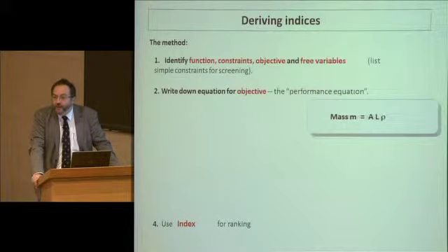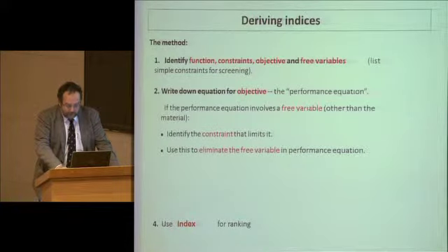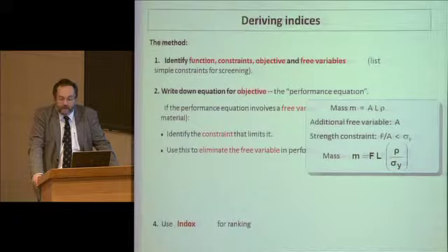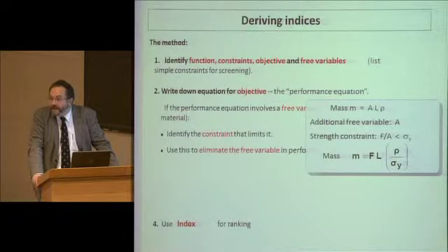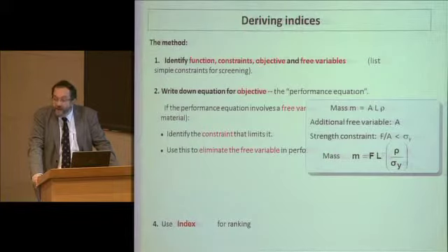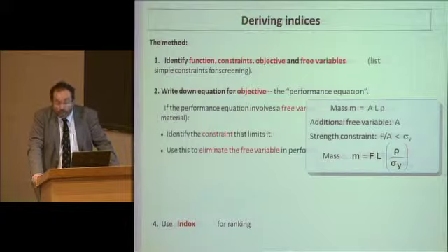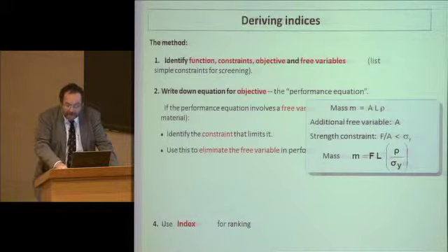So, if you want to enter the objective, you have the mass, which you wish to minimize. You want the constraint to be that F divided by A be smaller than the elasticity limit, and between the mass and the constraint, which must not be higher than the elasticity limit, you can see that the mass of the part you're looking for must be greater than the force times the length times the density divided by the elasticity limit.